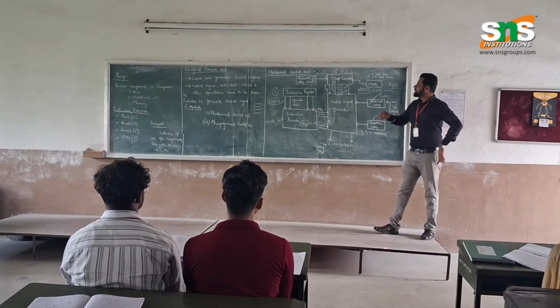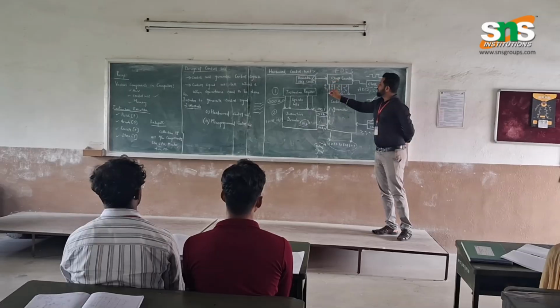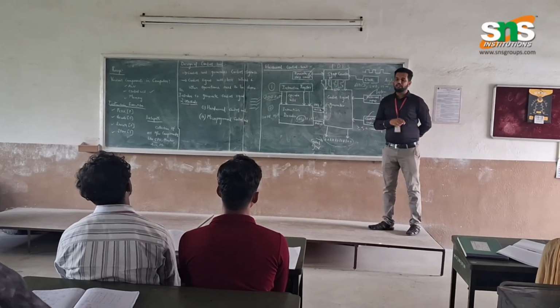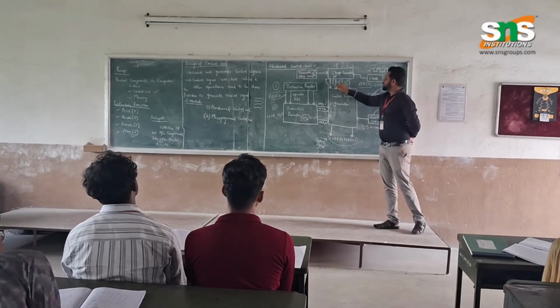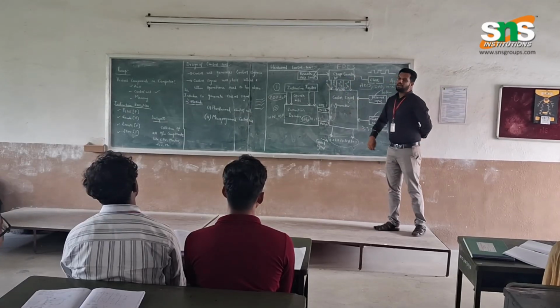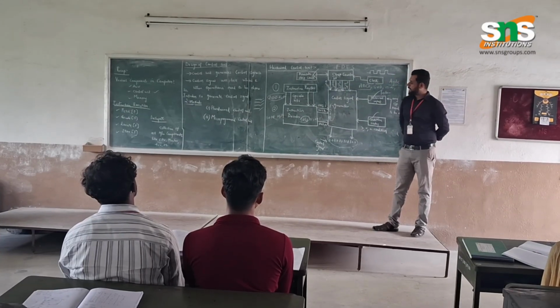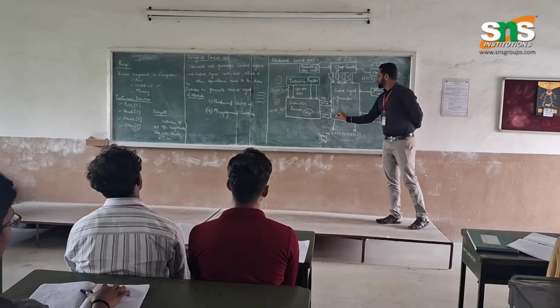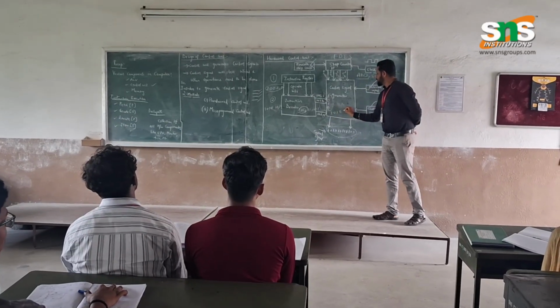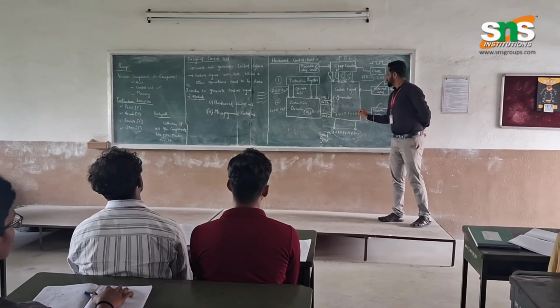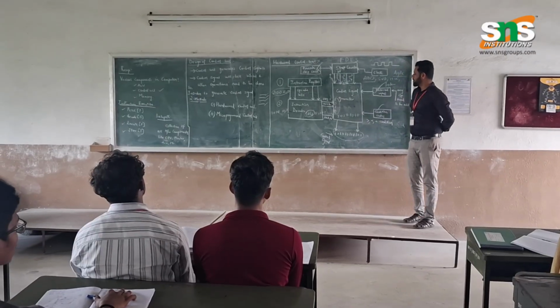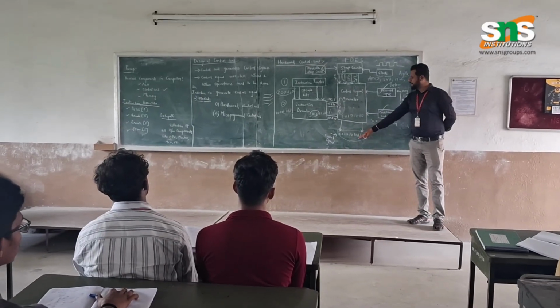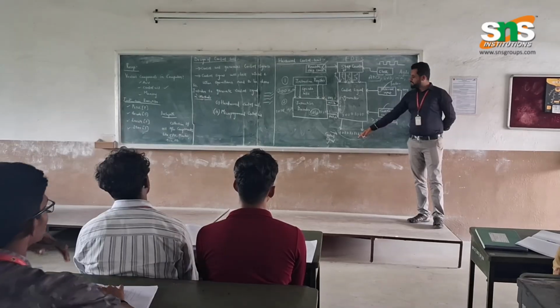So finally, this step counter will do the fetching process at the time T1. Then at time T2, it will do the decode process. Execute will be done at time T3. Likewise, the codes from the control signal generator will be generated using these different blocks, like 10101010. This is the binary code which will be sent to the computer.